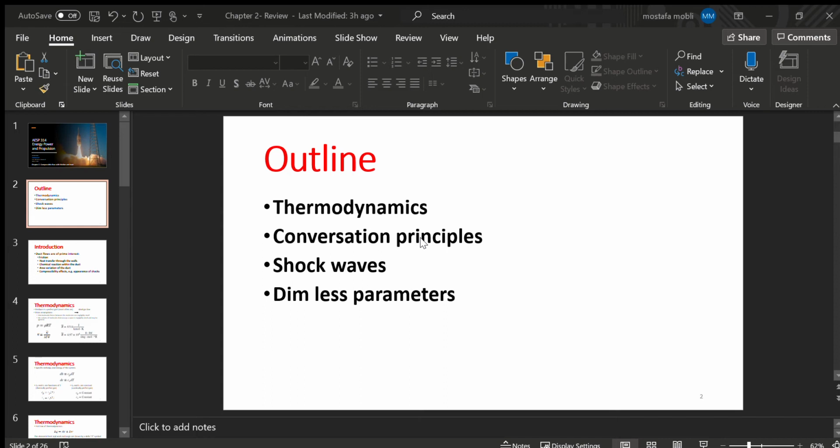We have to keep in mind that the reversible part of work is always related to the pressure of the system. So we can find the reversible part of the work, delta W reversible, by this equation, PdV. Okay, and the viscous stress relates to the dissipated energy from the system, which creates that inequality and essentially the increase in entropy, right?